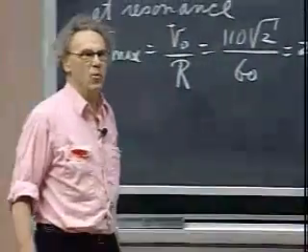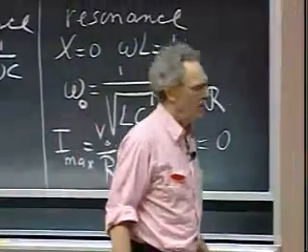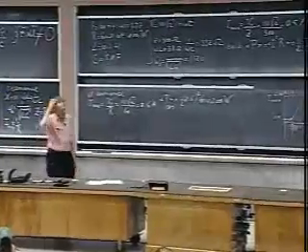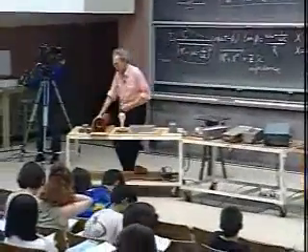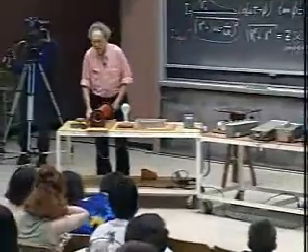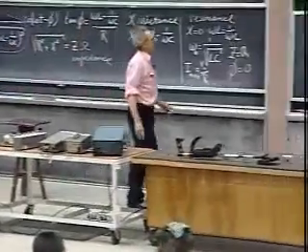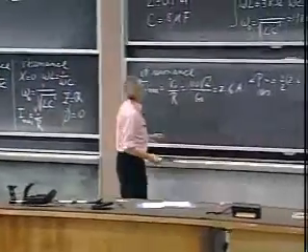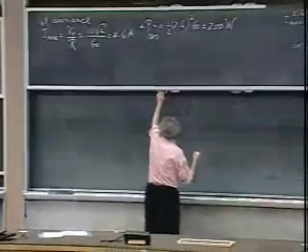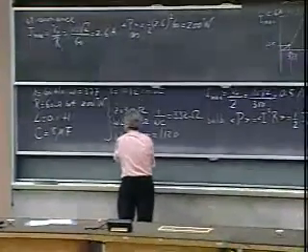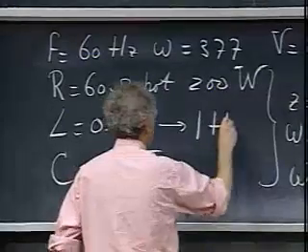I'm going to teach you a way that you can increase L, something that we have never discussed before. I have here ferromagnetic material, which has a value for kappa somewhere around 10, 12. Let's say it is 10 for now. So that means that if I bring that iron core inside, I could make this go up to 1 Henry.